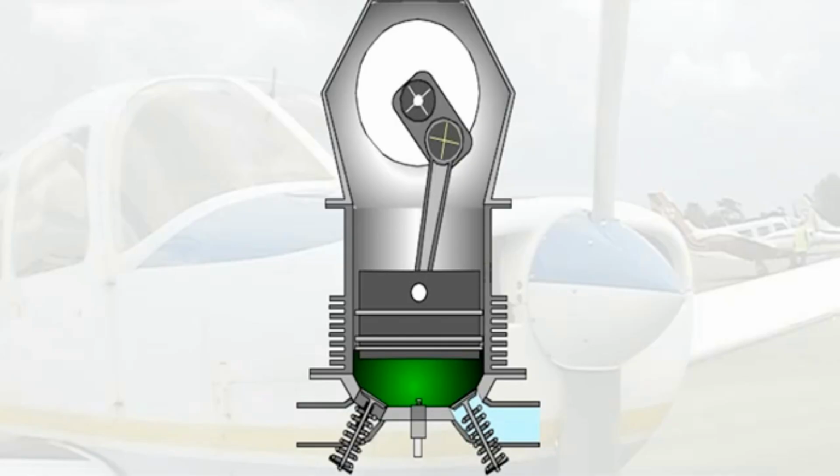To prevent hydraulicking, the engine must be rotated by pulling through on the propeller, after confirming that the magnetos are off before the propeller is touched.